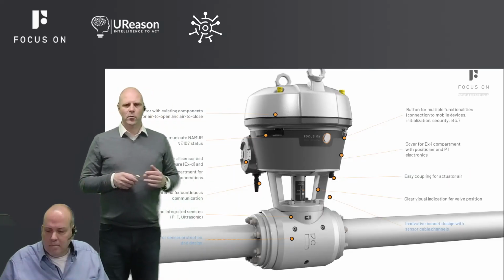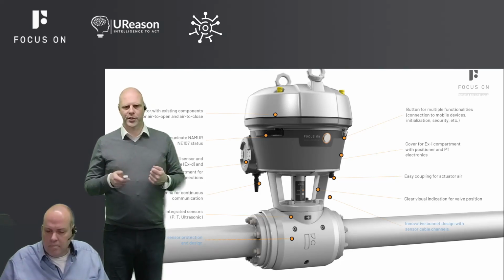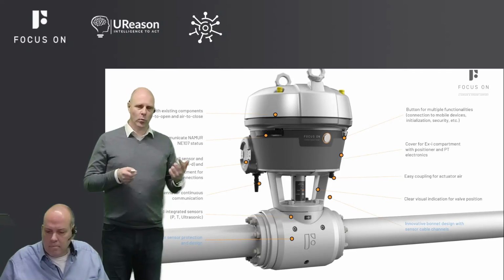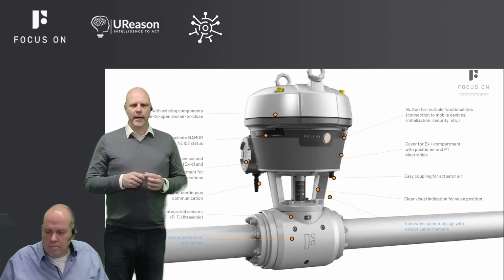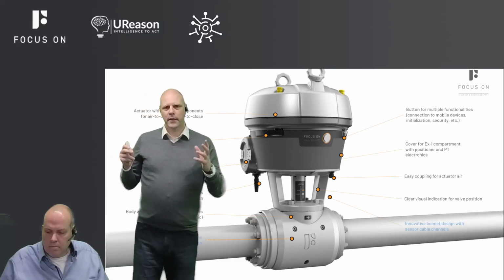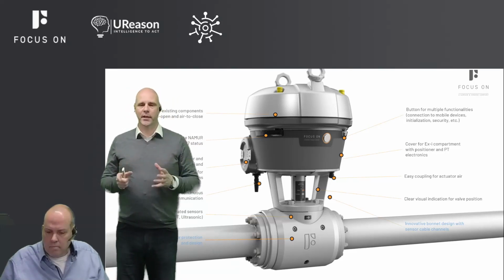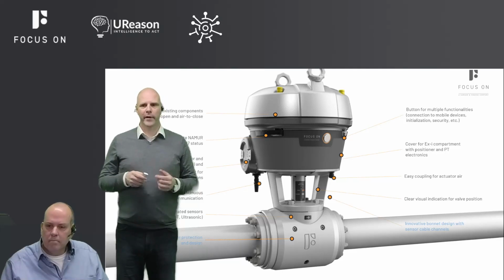So what is it? Well, in the basics, it is an integrated device. It's got flow, pressure, temperature sensors in there. It's got an actuator in there. It's got Wi-Fi in there. It's got one button to control it all. And it's got a computer in there. So it's an interactive device integrating a lot of sensors and an actual actuator, a globe valve actuator.